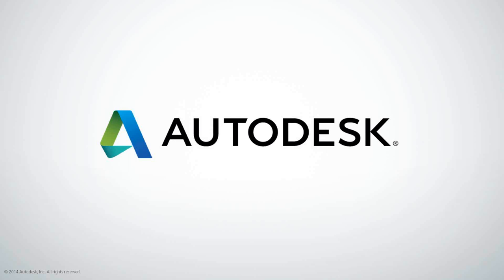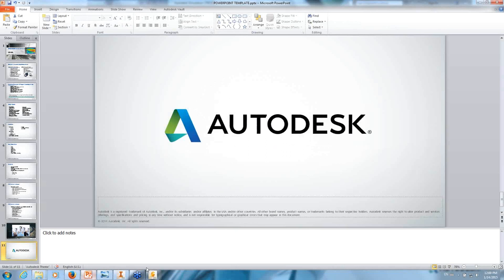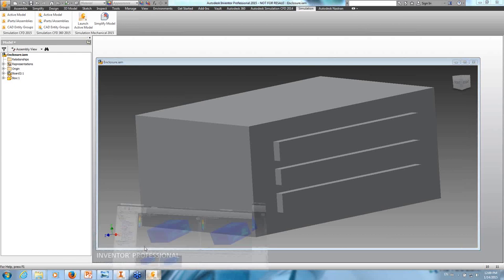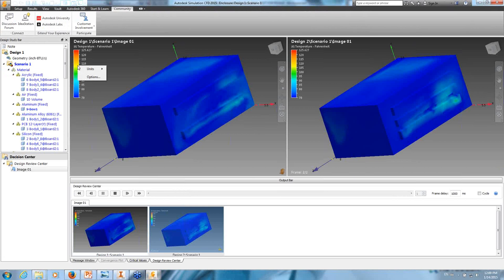The legend bar for different images on the electronics model, is it for one specific design build? It kind of picks the worst case legend range and then applies that to both when you do a side-by-side comparison. So that's why it was the same for both. You can then change the legend to whatever range you want for your needs. Like if you want to isolate it to a chip on the board and really make it pop out, as a designer would view at work.